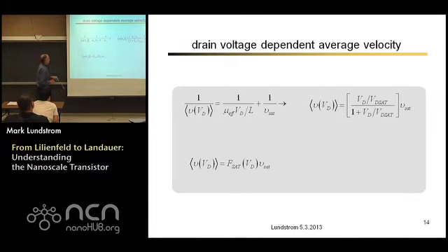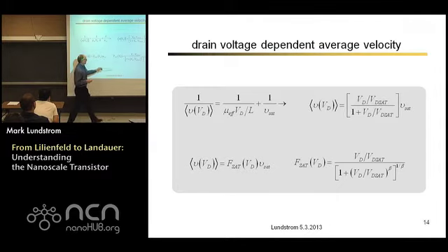Okay. All right, so we can write the average velocity as some saturation function times Vsat. And that saturation function now will make it just a little more complicated, because if we give ourselves just a little more flexibility, we can fit any transistor. And so this makes it a little bit empirical. So we'll just take Vd over Vd sat, raise it to some power beta, and we'll raise the whole thing to a power 1 over beta. People find that's empirical. It's reasonable, but it's empirical. You do that in almost any transistor, you can fit beautifully by adjusting beta just a little bit.